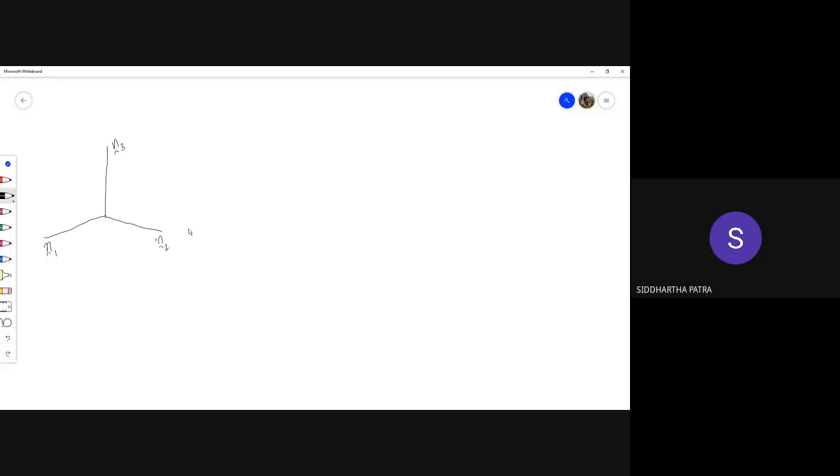So if it were any arbitrary Cartesian system, the stress components, as we discussed, on each plane there would be three directions of stress components, or rather tractions. Eventually giving nine components of the stress tensor. So for example, let's take the front face. On this one we'll have three components of traction. Which means I need a total of nine components to describe stress.